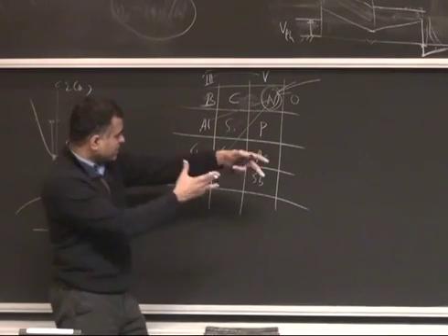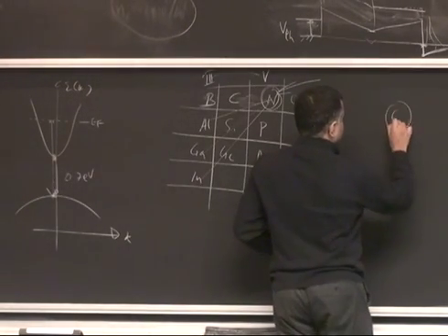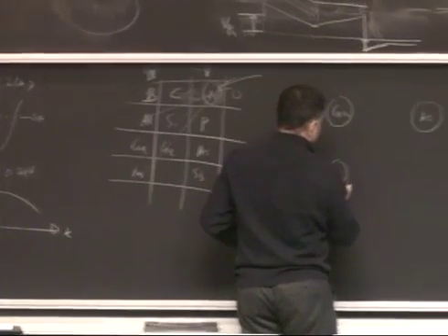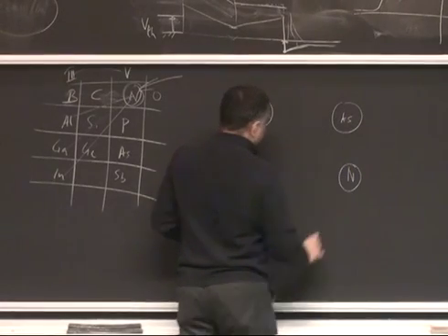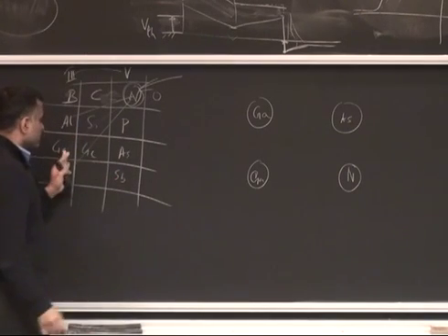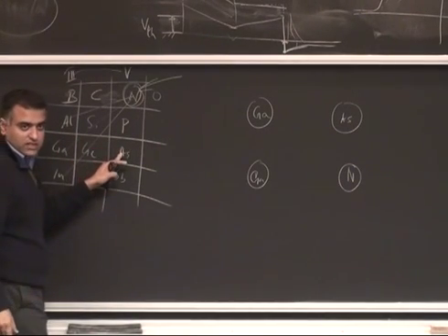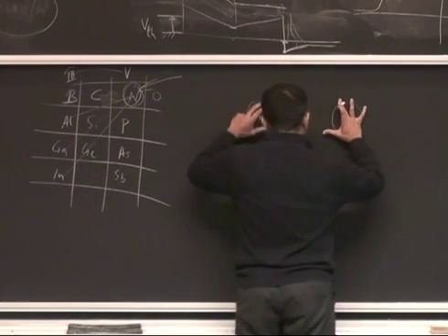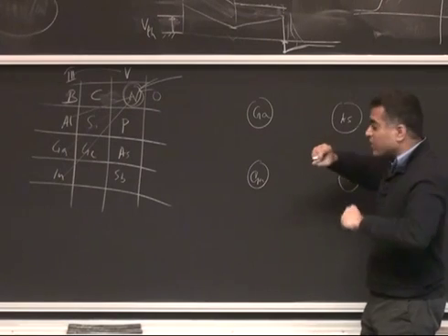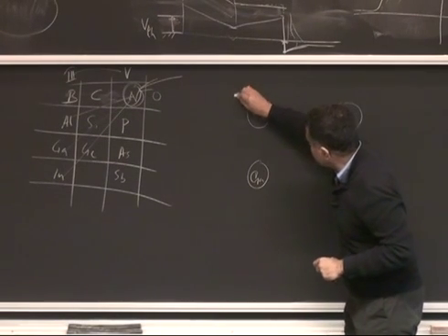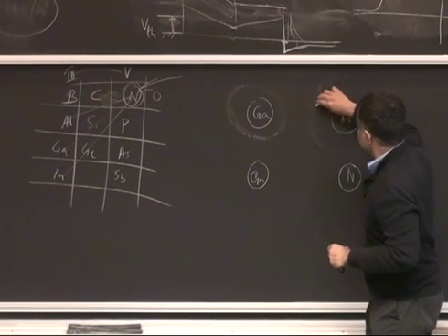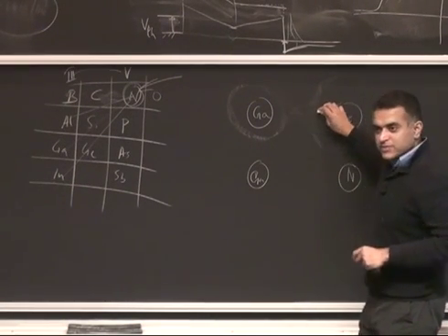So whenever you have a bond between, say, a gallium and an arsenic atom, or a bond between gallium and a nitrogen atom, these bonds are very inequivalent, in some sense. Arsenic has relatively lower electronegativity. It's not as electronegative, but it is more electronegative than gallium, so it wants to pull away the electrons from gallium when we form a bond. If you were to sketch the electron cloud, it will be maybe something like that, and this will be a little bigger, and so effectively, it's slightly polar.